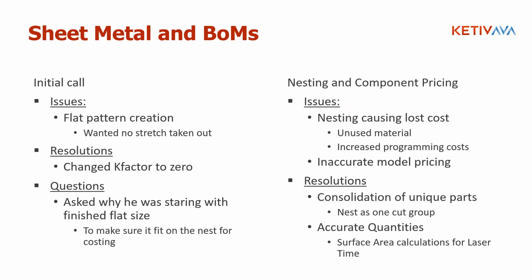Now, this came up a week or so ago, and being in Lifeline, I get calls with issues, and the initial call was they wanted the flat pattern for the sheet metal to have no stretch taken out. It's like, okay, that's different, but okay. And so the solution was, change the K factor to 0, gave them the flat pattern.